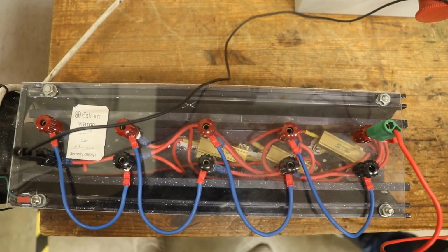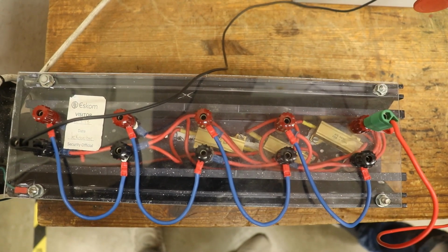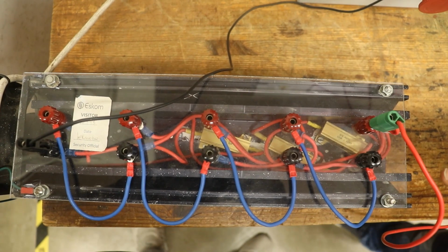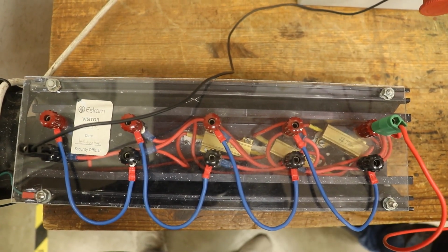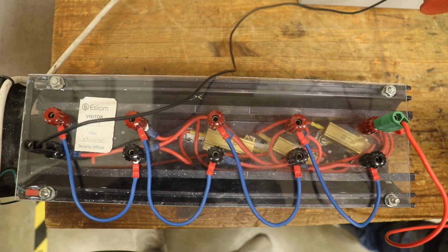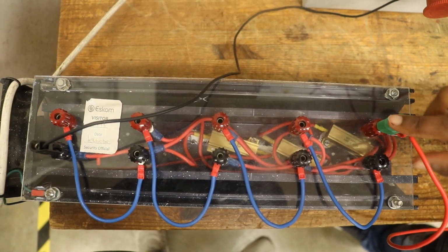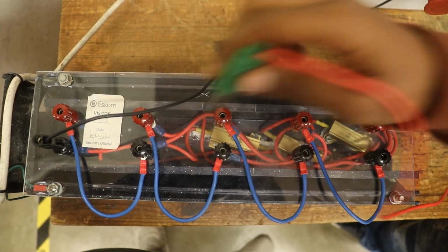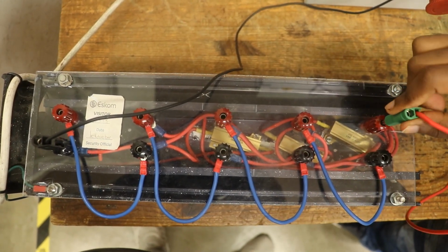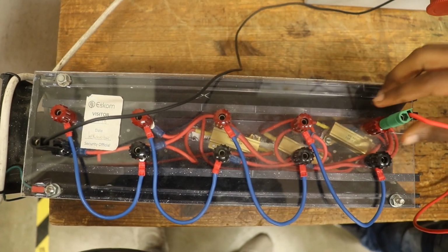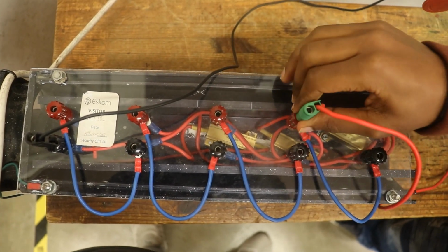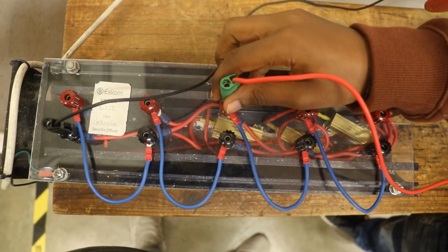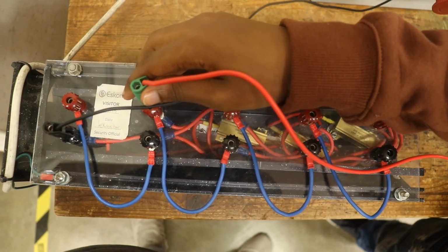So for the last part of our lab, we're going to be looking at our 500 ohm resistor bank, which we're going to be using in our efficiency test. Now this resistor bank has 500 ohm resistors connected in series on the inside, and as you move your connection terminal along the various terminals, you'll be reducing your resistance. So in the first position, you will have a 500 ohm resistance. If we move it to the second point, you'll have a 400 ohm resistance. Third point, 300 ohm resistance. Fourth point, 200 ohm resistance.